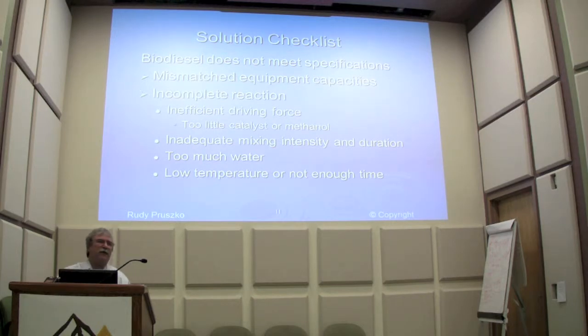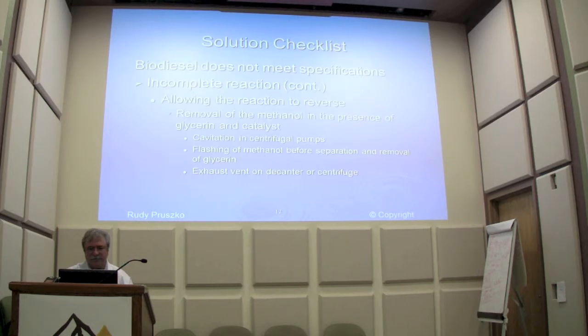Yeah, if you're going between the first stage and the second stage, you want to get out the bulk of the glycerin. Now, remember I said a little, if you're going to err with biodiesel going into the glycerin, between two stages the reverse is true. A little bit of glycerin can err in that first stage. It's just separation, just to take some of the glycerin off before you go to the second reactor.